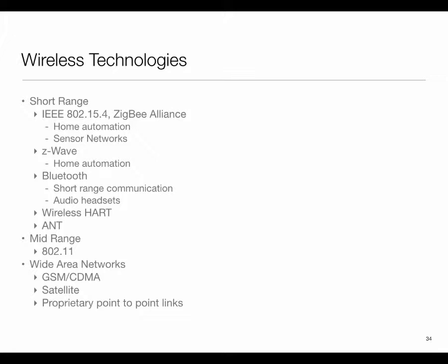One of the big things which happened in Bluetooth over the past two to three years is so-called Bluetooth LE, or low energy, or Bluetooth Smart, which created a special mode catering to sensor-type devices. Devices which need to talk sporadically at low rate but need ultra low power. You want them to be able to sleep for long times, wake up, and then without a lot of overhead, send a message out. So Bluetooth LE is a big change. A lot of our wearable sensors end up using that. We'll go into more detail on ZigBee and this in a later lecture.